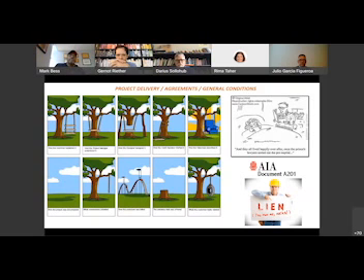Then we transition to a next phase, which I group together as project delivery, different types of agreements that we would have. And then we start taking a look at a couple of documents. Project delivery is something that I really like a lot. We look at some of the characteristics that impact the different types of delivery systems, whether it be design-bid-build, design-build, or construction management, and the two different types of construction management, as agent and at risk. And we do circle back and have that discussion about integrated project delivery systems.